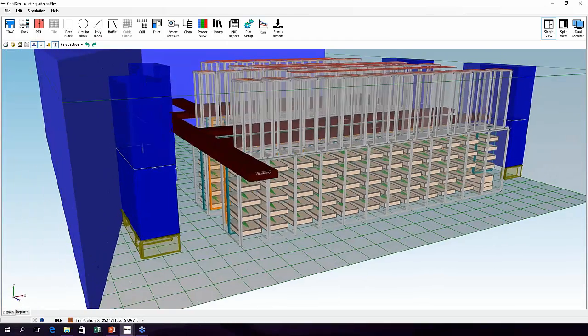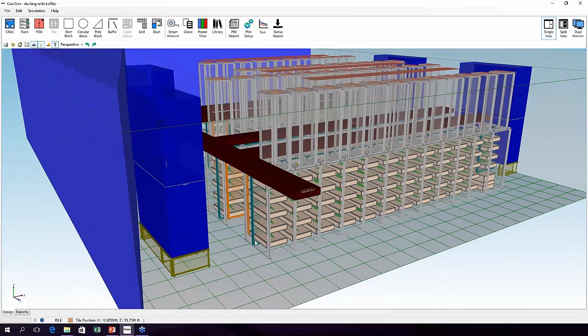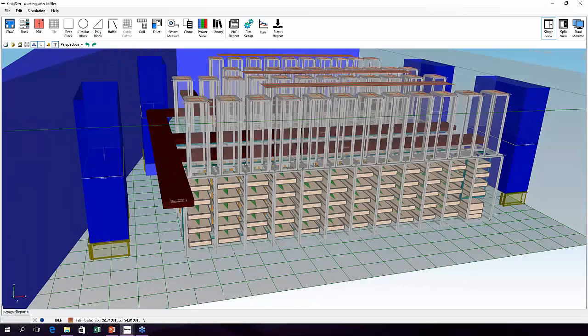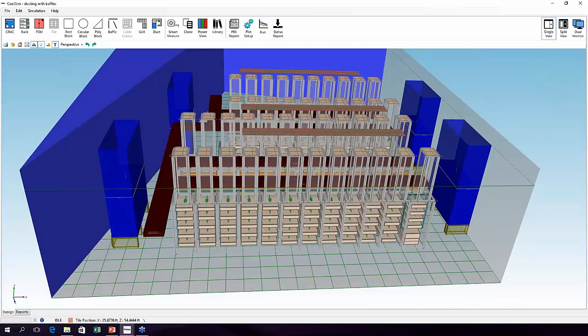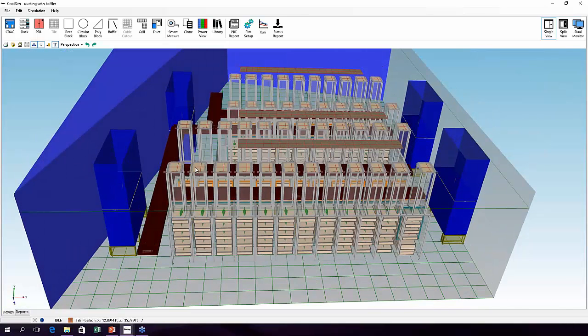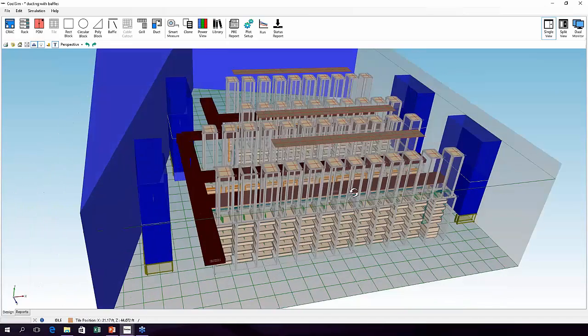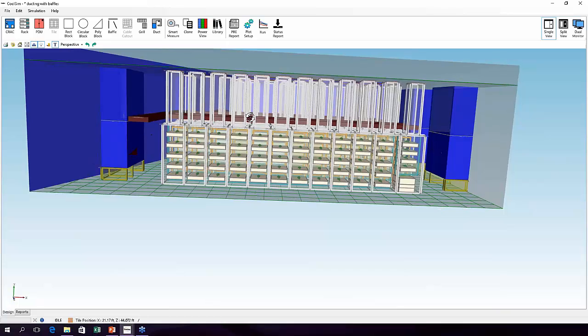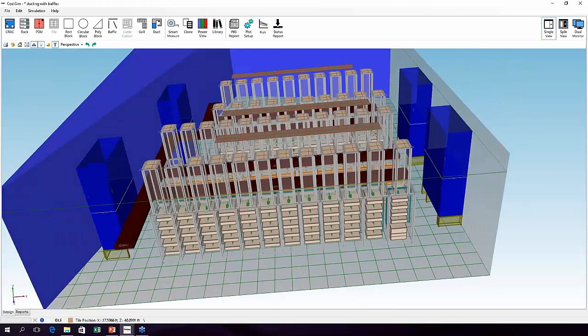They're blowing front to back. The user has put a rack rail in, so there's some leakage there, and a front face on it. So that all looks pretty good. I mean, it would normally be fine. Now what the user remembered to do is to punch a hole in the ceiling so that the air can get out of that chimney. It's very easy to forget that little guy because it looks like it's got a hole in it, but it doesn't because the ceiling is transparent. So this looks pretty good.